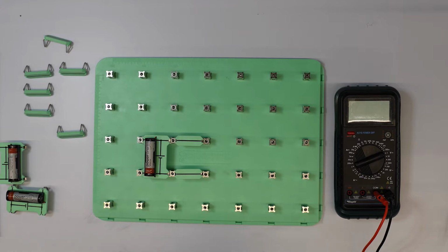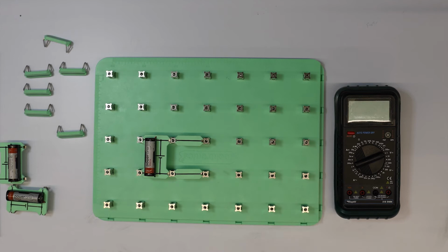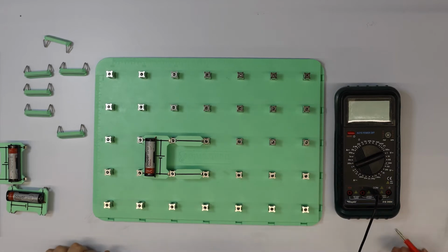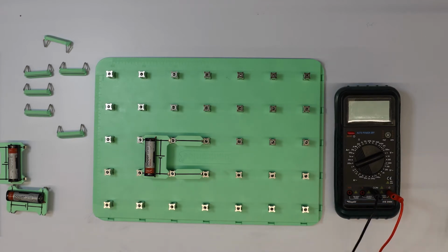Right, okay, so a few things to note with the multimeter. We have to make sure that we connect the leads in the right ports on the bottom of this. So here I'm going to connect the black lead into the black COM port, and then I can connect the red lead into 3 different ports. These here are for voltage measurement, for current measurements, and the one here, because I'm measuring voltage, is on the right hand side, so I need to make sure that that is slotted into that part of the voltmeter.